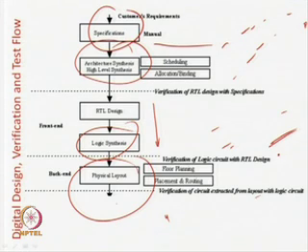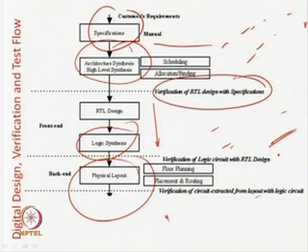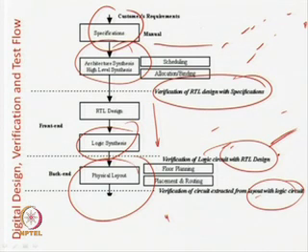These are the first few steps of digital VLSI design, and at each partition dotted line you can see verification of RTL with specs, verification of logic synthesis with RTL design, verification of circuit extracted from layout with logic circuit. So, what does this verification imply? At this level your design was at some specs level, the block level or architectural level. From here you have got an RTL design. So now there is some translation, and you have to see whether the translations are valid or equivalent or not. So, we require a verification here.